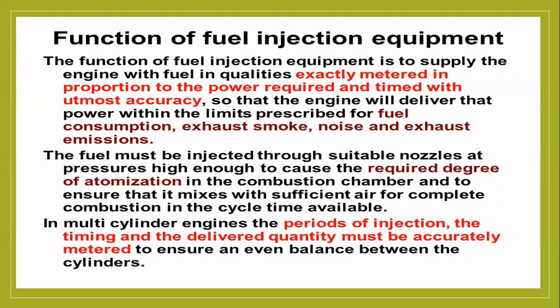So 8 volumes of air are compressed into 1 volume. That is called the air-fuel mixture, in the gasoline engine. Here in the diesel engine, air alone is compressed 16 times. Then, where the temperature is very high, the diesel is sprayed inside this air.